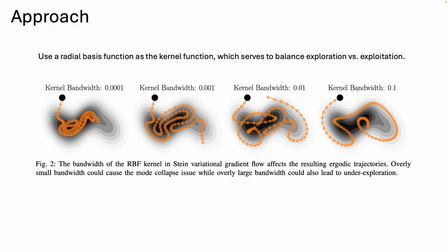How you shape that, and even the choice of the kernel function in general, is very much a design choice. Some papers use a square, some use a uniform distribution, some use a Gaussian. It's a user choice, and you can also use it as a metric for exploration versus exploitation. If you have a tighter basis function about your point, you might favor these high density regions. As you spread that out, you might get more explorative behavior. So this is like your coverage area, basically.